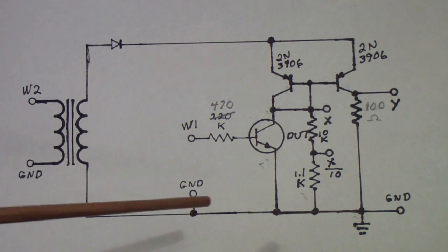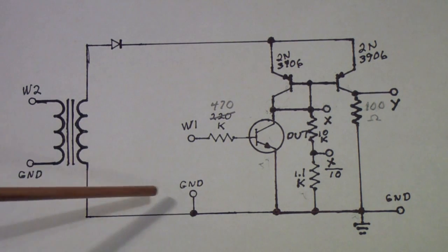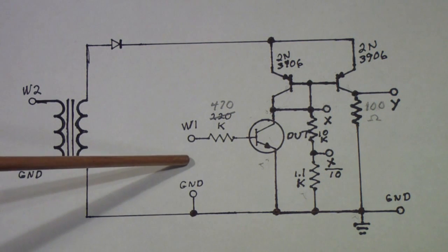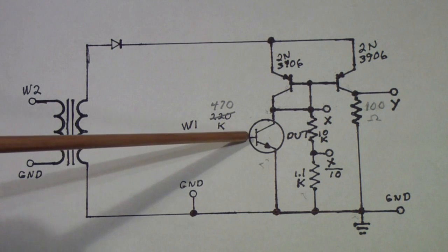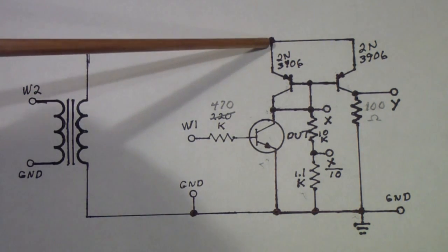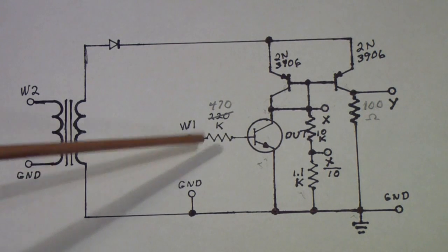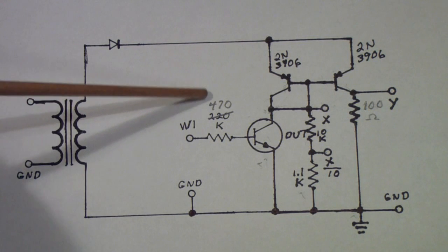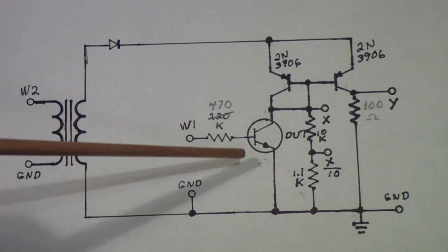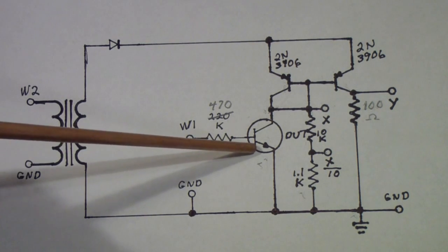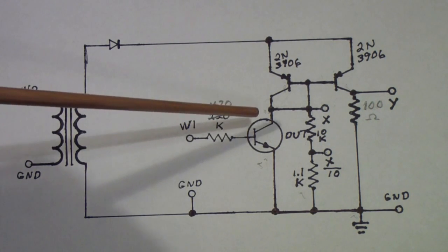So there are three improvements that have been made. One is using a sawtooth instead of a triangle for the collector voltage. Another is using a lower base current, in other words, a larger base resistor, to get the transistor into more of its normal operating range.